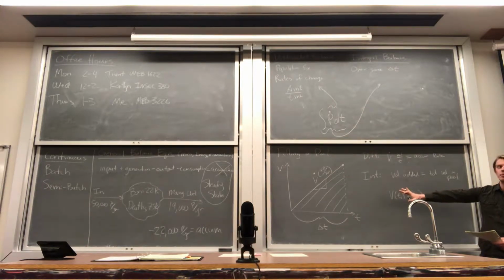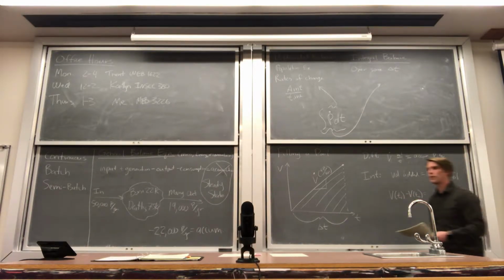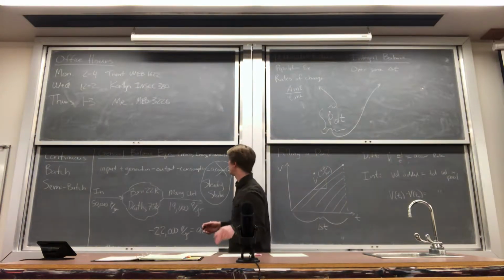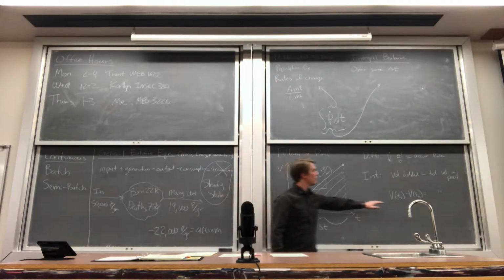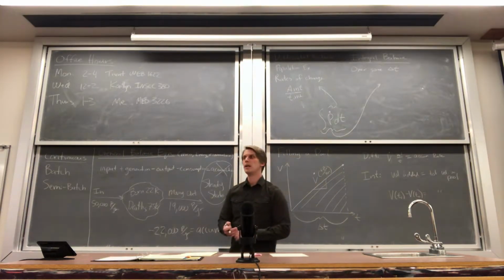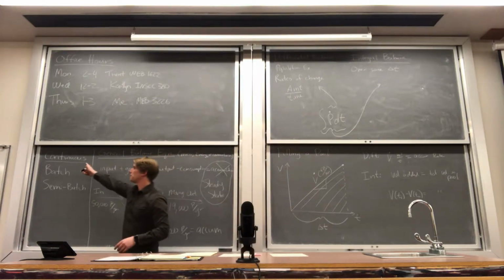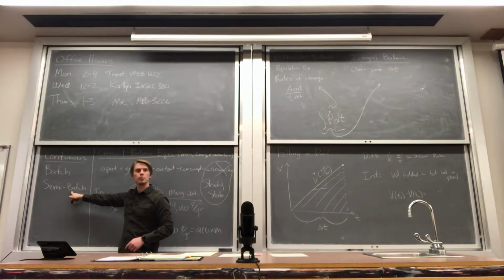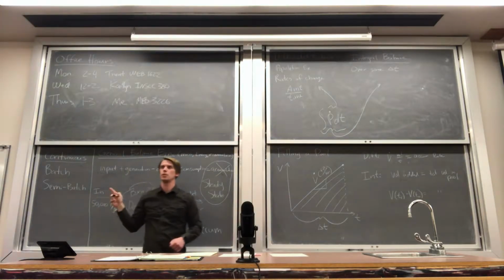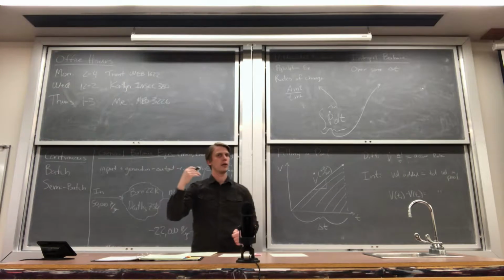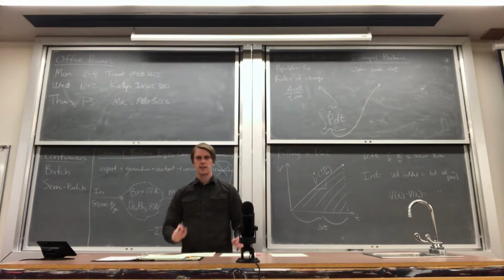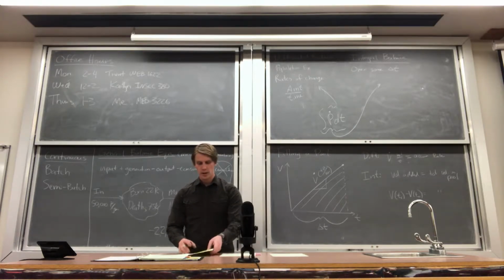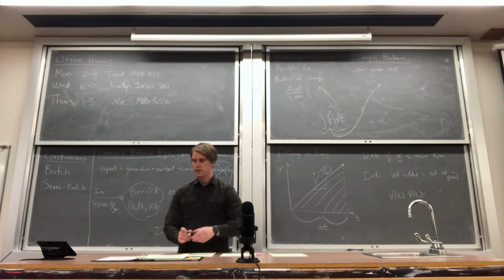So these examples seem a bit trivial, but you'll find that sometimes it's best to think about things as a rate of change, and sometimes you'll have to think of them over a course of time. So in a continuous process, typically we're going to be using a differential balance. In a batch or a semi-batch process, we're typically going to be thinking about the material balance as occurring in an integral form. Any questions about that? It may seem just like semantics right now, but it'll all come to fruition soon enough.